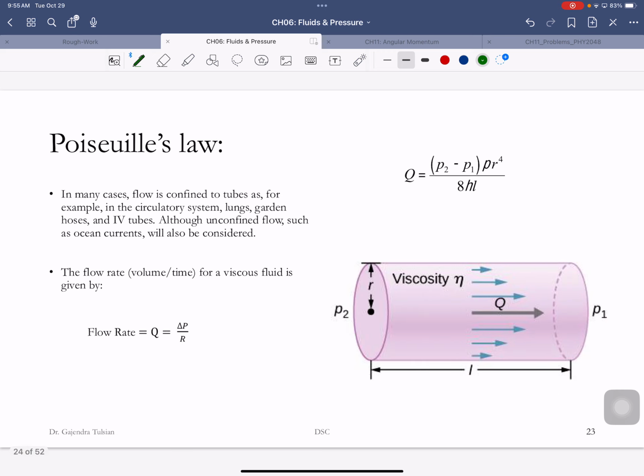All right, so again, flow rate is the pressure difference divided by the resistance to flow. And so Poiseuille's law: when blood flows in a nice laminar fashion, the resistance is given by Poiseuille's law, and resistance, like you saw in the formula before, has pi r to the power 4.